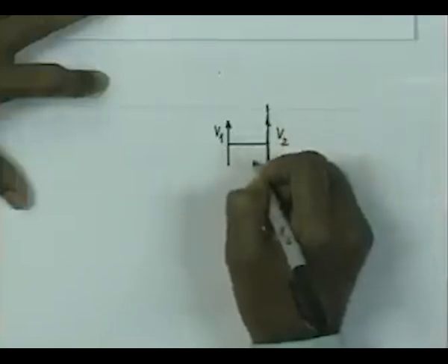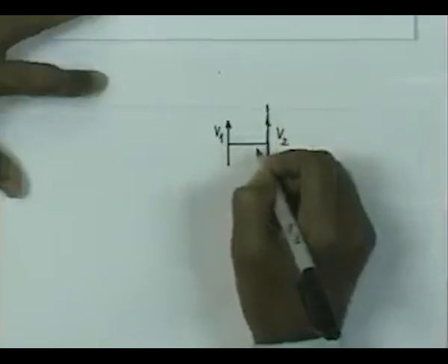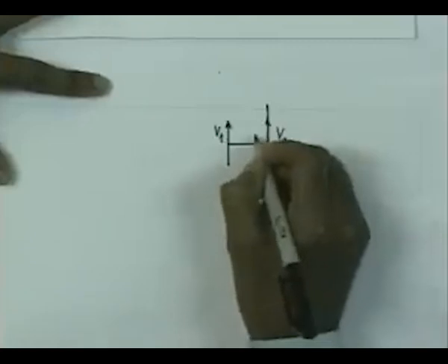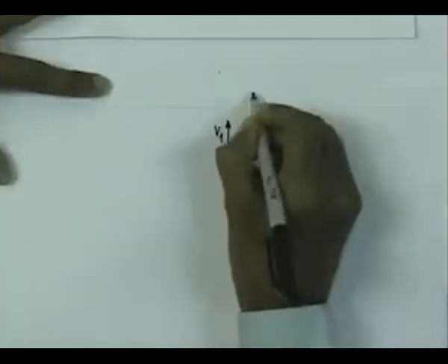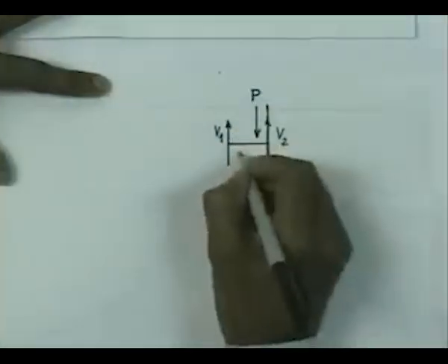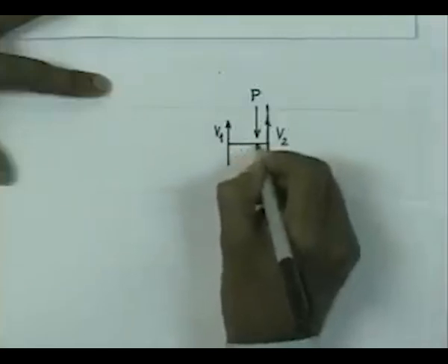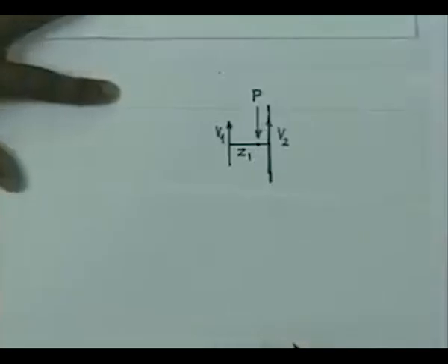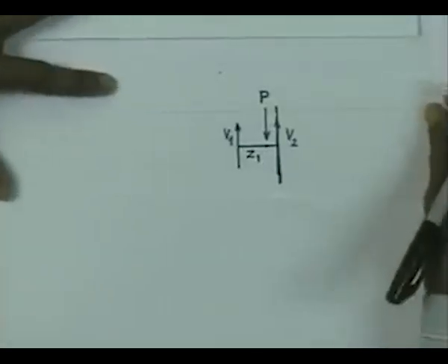and so the sum total of these two will be passing through somewhere here, and we must see that the external loading is also passing through the same point, or it must act on a plane which passes through the same point. So, if the external loading is acting on a plane, let us say somewhat like this is the external load, then let us consider that it is acting at a distance of z1 from the left arm, then we must see that the moment is balanced.